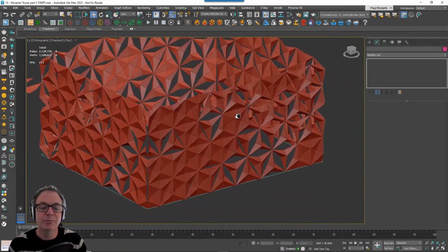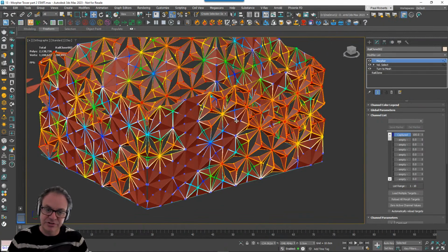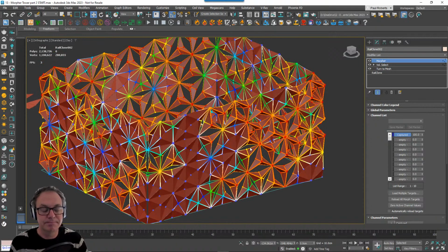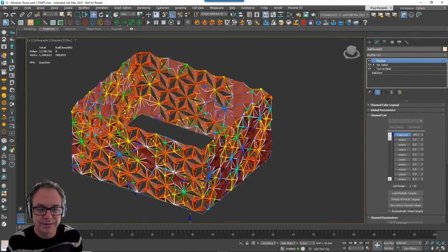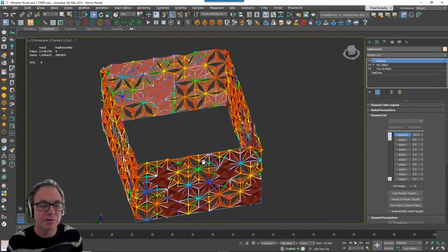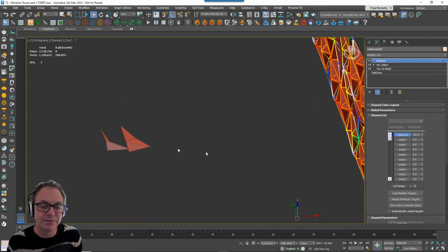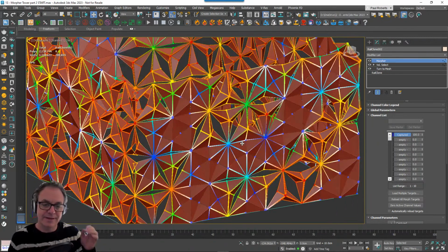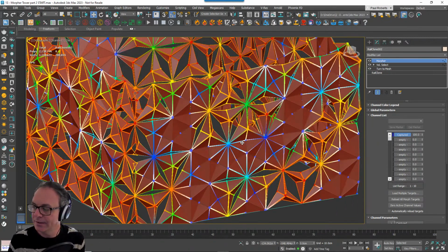So I'm aware that I'm skimming over that, but if you're interested in that part, if you missed the last month, then you can see that in the August live stream, this technique with using volume select and morpher modifiers, and that will help you to learn that bit. But it was more about how you can use this simple triangle to create this quite interesting facade shape. So I found that to be an interesting case to help answer.